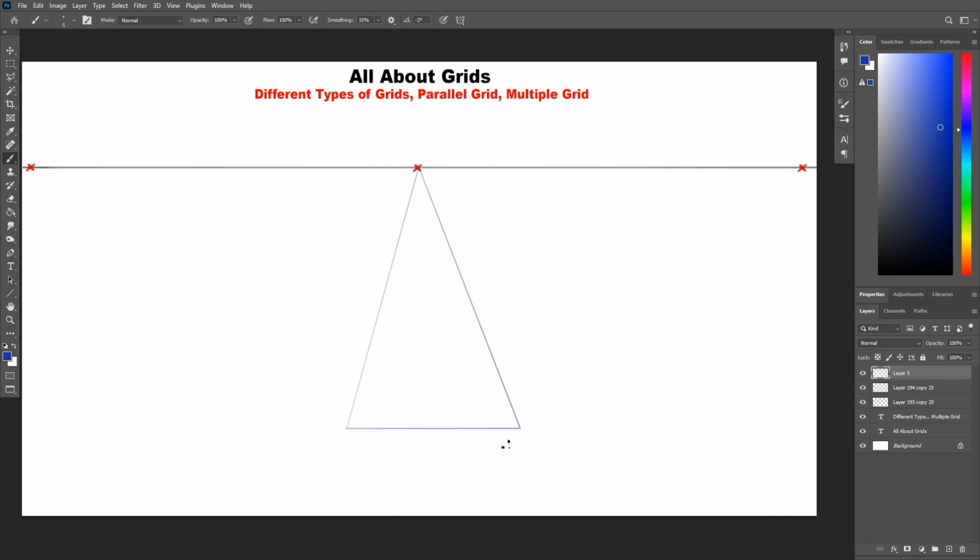We draw the first edge and connect it back to the vanishing point. We are using 1-point perspective here, so we end up with this shape. Now let's draw a 45-degree line from the corner of that edge all the way to the horizon line. Let's connect the first intersection point with the perspective line and make our first rectangle.